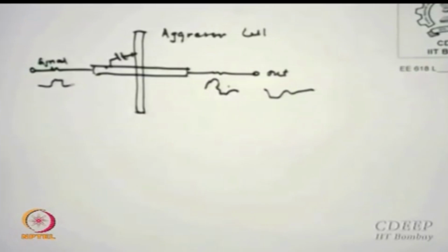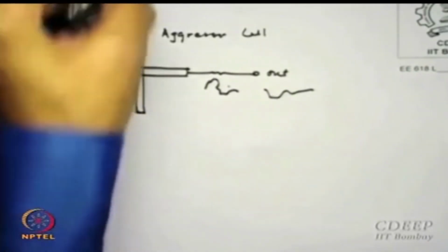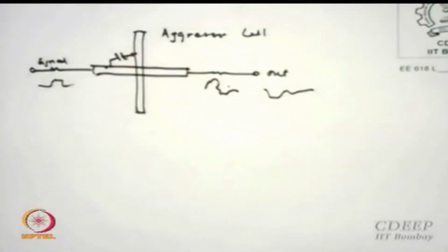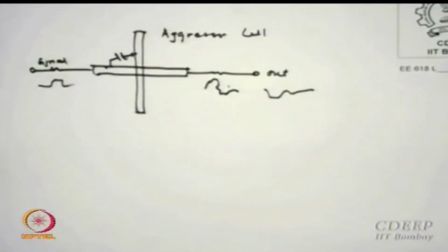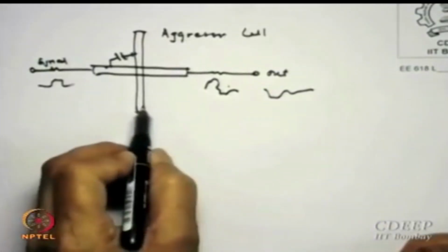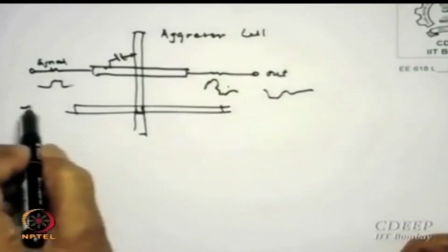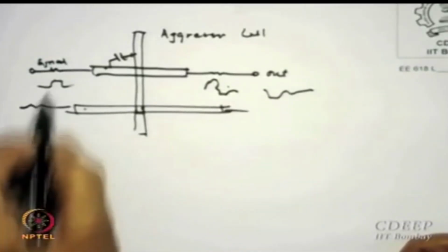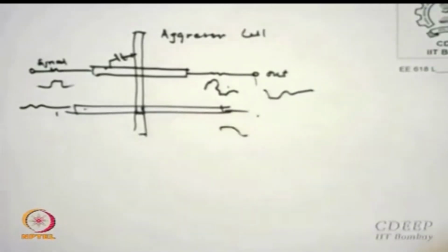Further, there is also an issue if the data is flowing in this direction or in this direction in the aggressor, as that may also change the output patterns. Ideally I do not want this to influence. So if you have an aggressor here, I have another interconnect line, with the same signals going to both, and I take the difference of the outputs as well.